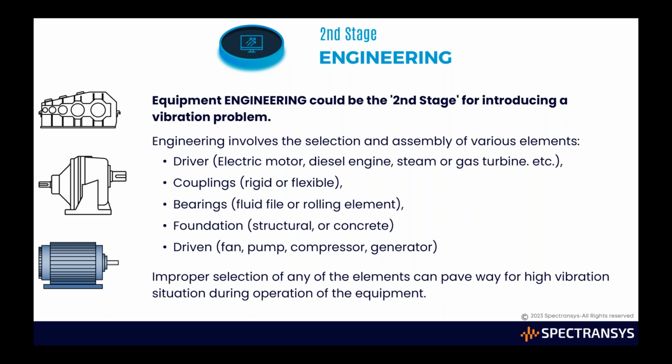The same is the case with the bearings, or with the foundation and all those things. Sometimes you select a pump with certain head, pressure and flow conditions, which is primarily considered for your application purpose, and then the driver, an electrical motor, may not be properly selected. It may be either higher rated or under rated. In both cases, if the motor has a higher or lower capacity and they are coupled together, then you will definitely face some vibration problems. So when I say the engineering stage, this is what is happening behind the stage. As a vibration analyst, when I start analyzing the vibrations under these conditions, it is not easy for me to identify exactly where these problems lie.